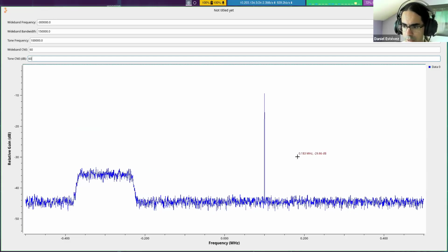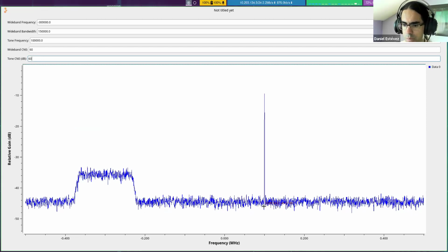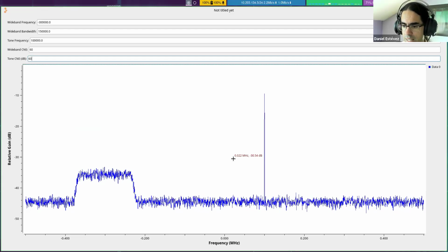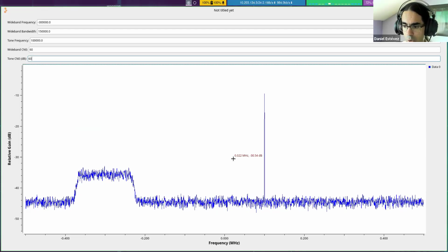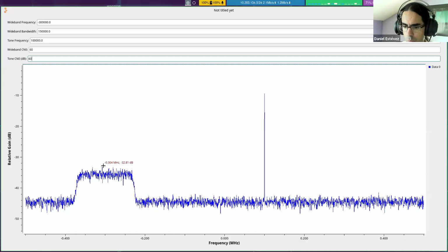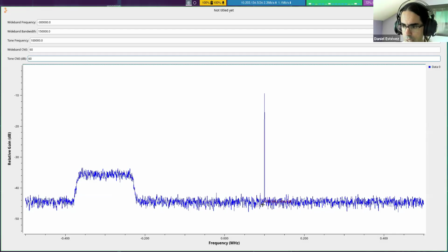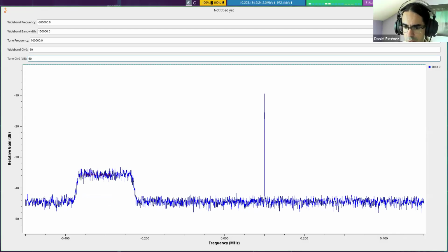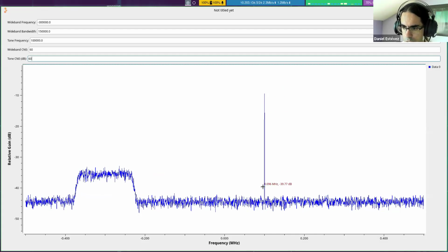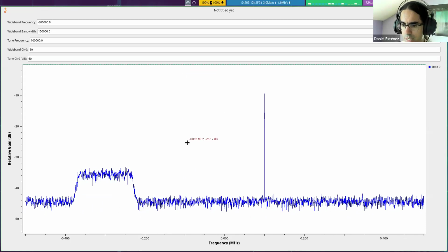And it doesn't seem like so on the FFT, on the spectrum. And the reason for that is, well, the spectrum is not a great tool to see the power of signals directly. We can see how much power is at each frequency, but to compare the power of this thing, which is extended in frequency, with the power of this thing directly, requires some calculations. Basically, we need to add all the power in here and then compare it with the power in here, which is concentrated pretty much at a single point, as we will see later on.